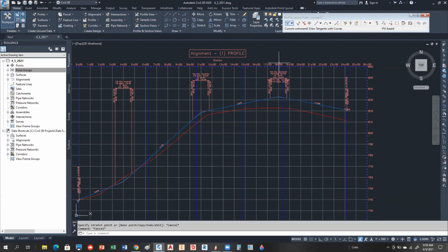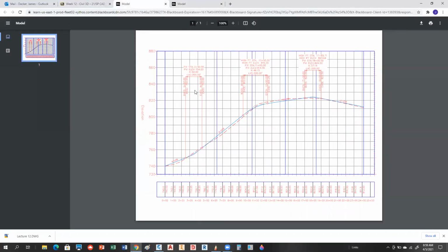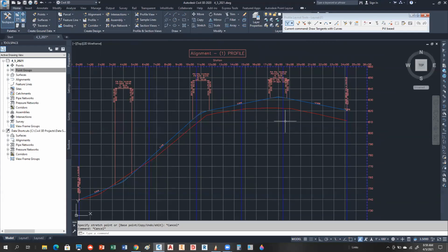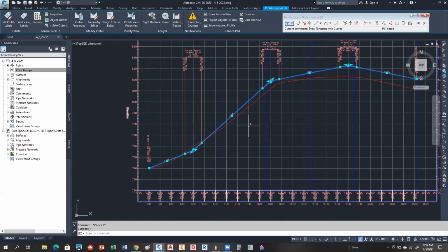So what we're going to do is get this one to match what I have on this one. I'm going to want to change the lengths of vertical curves on these, and I'm going to want to change some of the percent grades. Okay. So if you have that copy handy, great. If not, I'll get you through it. Okay. So we're going to click on this profile and go to this grid view here. Okay.